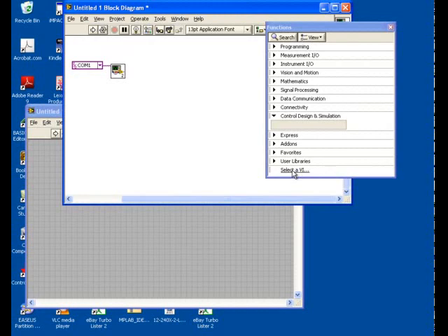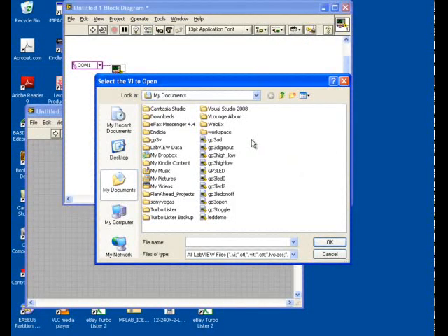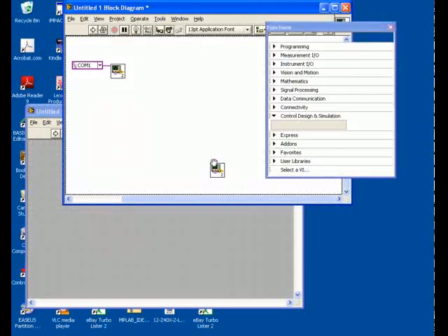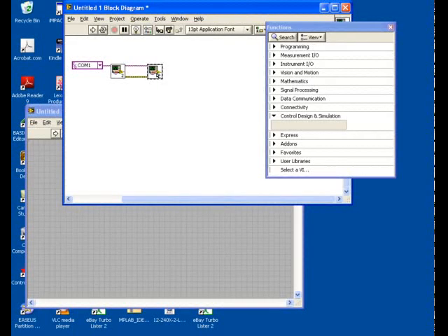Now what I'm going to do is make this program, or this VI if you will, light up the LED on the GP3, and I have a wire going from the LED output over to one of the analog to digital channels. So we'll also look at the voltage coming off the LED pin as we change it. So I'm going to pick my GP3 LED on-off block, which is another one of the examples, and I'll connect it along there.